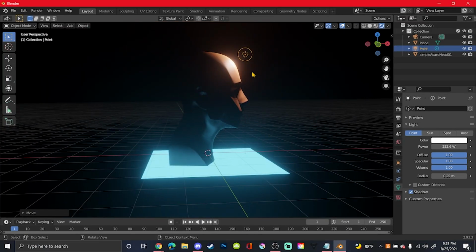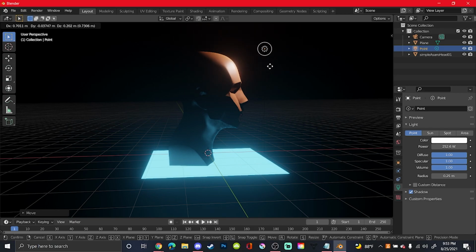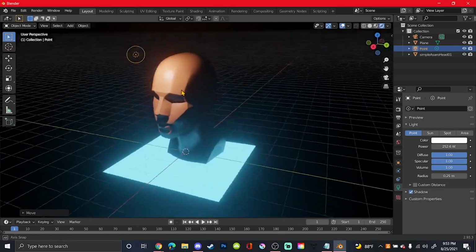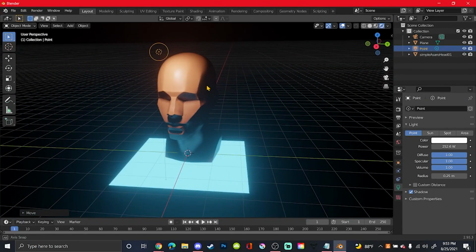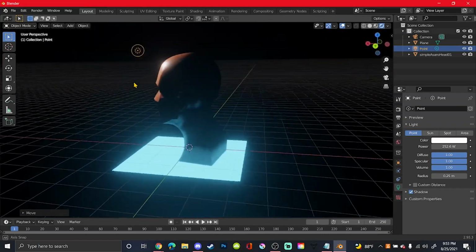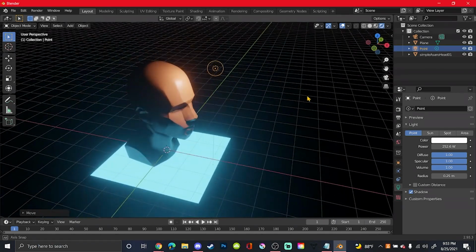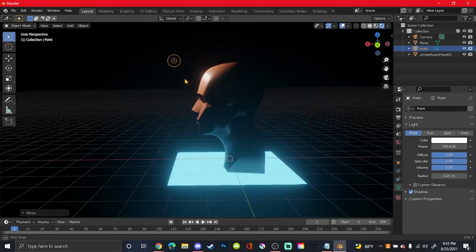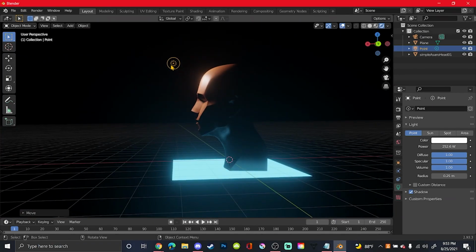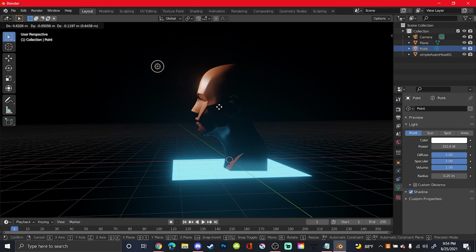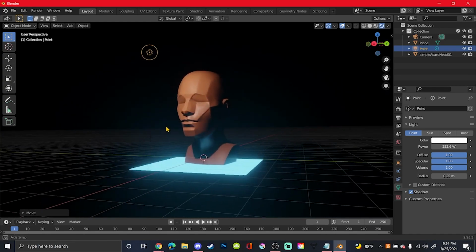Okay, so in 3D space, you just press G, move it, then click to place it. Now you hit middle mouse to rotate around, check to see if everything's right. If you don't like it, you can align yourself, click the point, press G, move it further out.